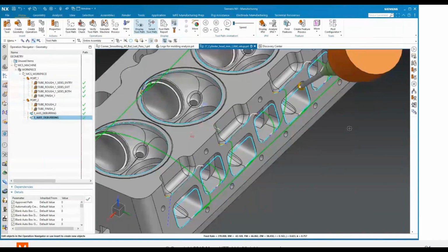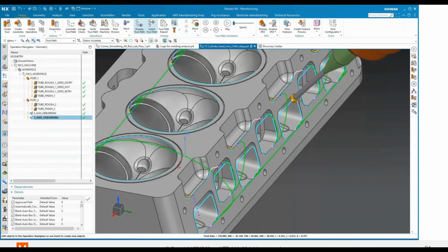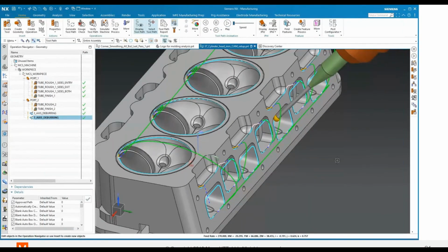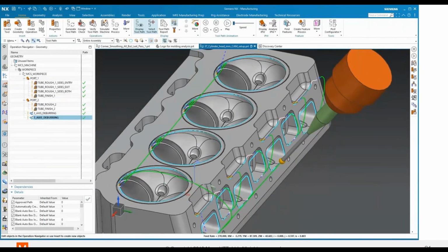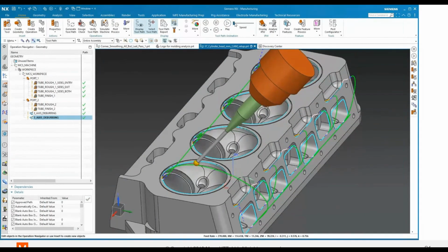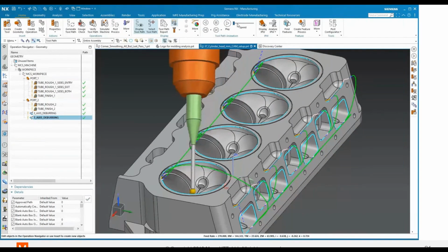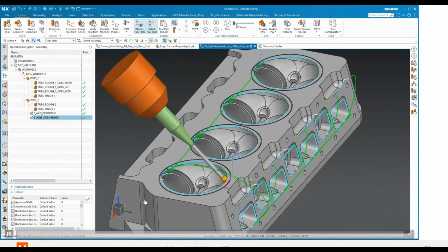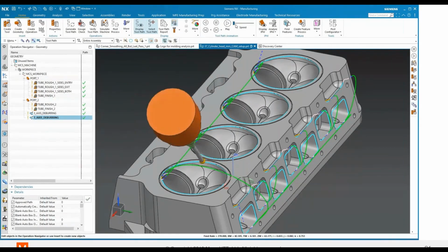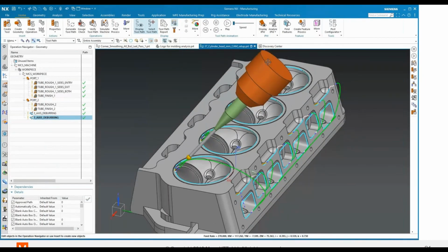And again, here the setup is very simple, although in this case we are letting the tool axis be automatically defined by the operation. So I'll go through one of these slowly so you can see that. And now let's jump over to the larger ports here. So a great technique to quickly achieve smooth deburring, even on these complex parts with complex machine kinematics.